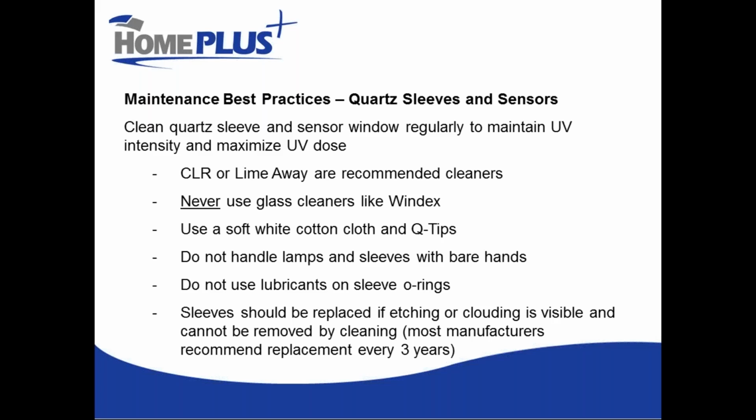And a couple of other really important points: absolutely never use glass cleaners like Windex on your sleeves. They contain organics that will leave a residue that absorbs UV light. It'll look really clean visually to your eye, but not to the UV light. Don't handle the lamps and sleeves with bare hands. Wear gloves. Don't use powdered rubber gloves. They tend to leave a residue behind as well.